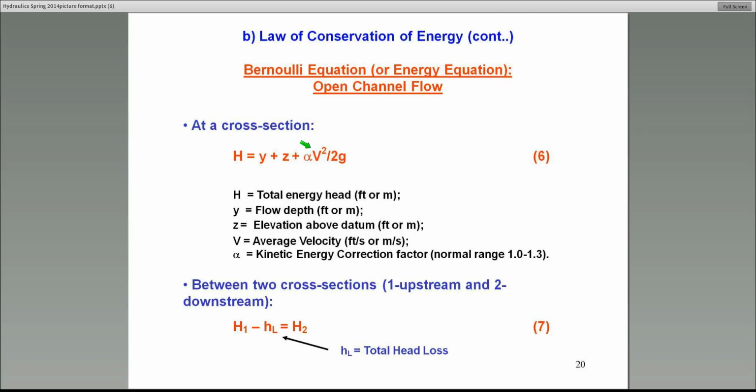And as you go to the center of the channel, the velocity increases and reaches the maximum value. So it's a non-uniform distribution. But the fact is you're assuming a uniform velocity distribution across the entire cross-section. And the price you pay there is, of course, that's not an arbitrary assumption, by the way. You make that assumption so that the same flow volume is going through both cross-sections, both the velocity distributions, the actual and the average.